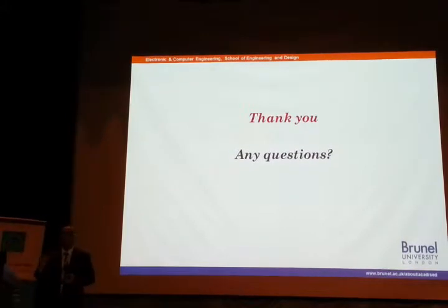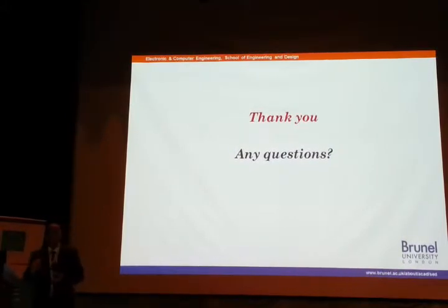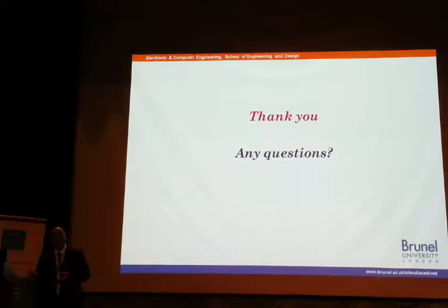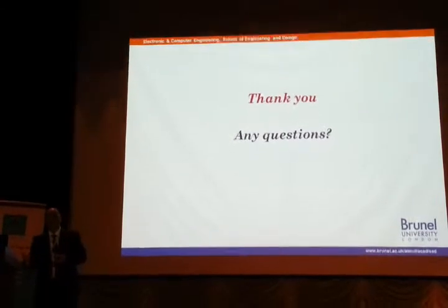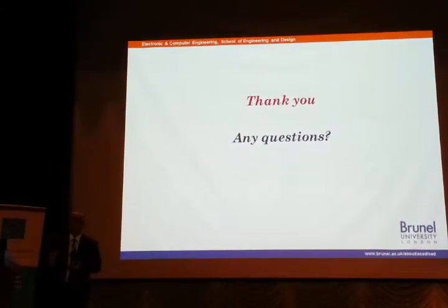We can do that. However, these devices operate at very high switching frequency, okay? Now, if I'm talking about low power applications, that's fine, no problem with that. But if I'm talking about tens, hundreds of kilowatts, even megawatts, now switching is very, very important here.